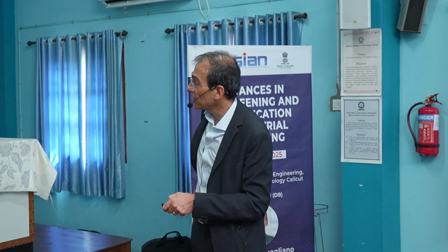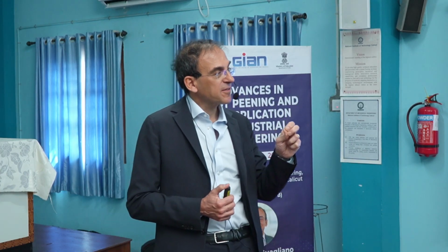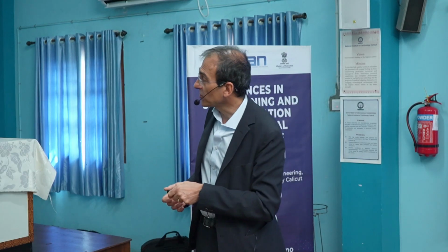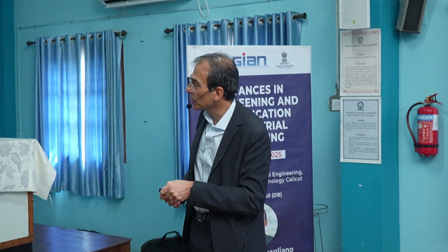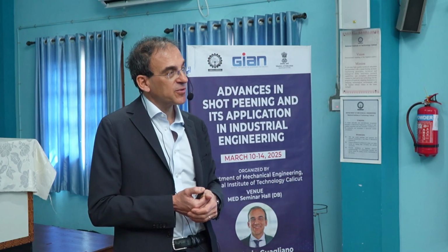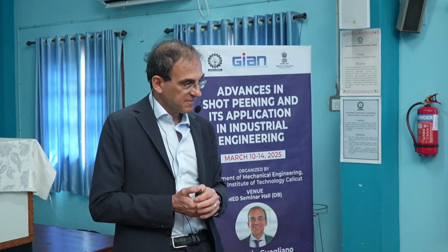Okay, and we can also develop some special nozzles, like this one, to make possible shot peening in details that are not easy to reach. That is to say, we need some particular geometry of the nozzle to go into these small details where the conventional, usual nozzle is not effective.